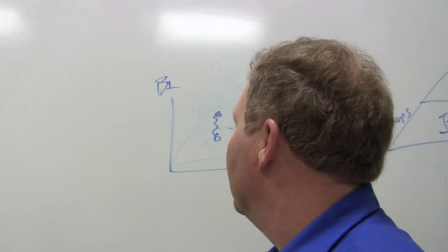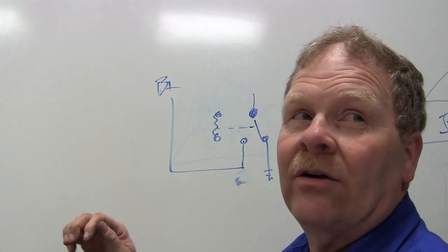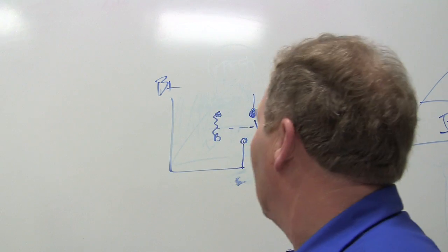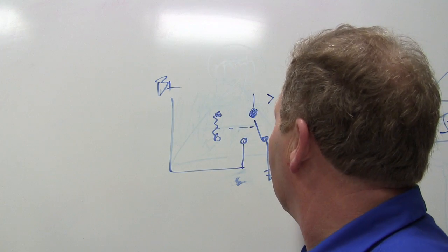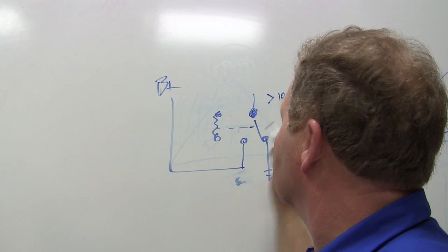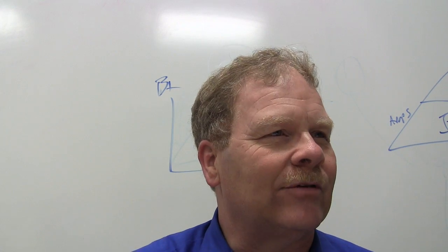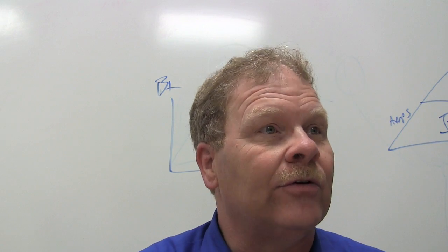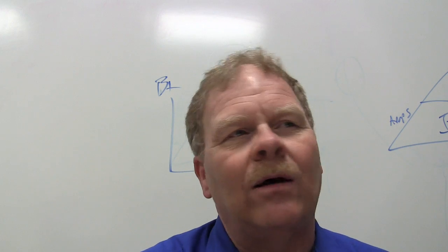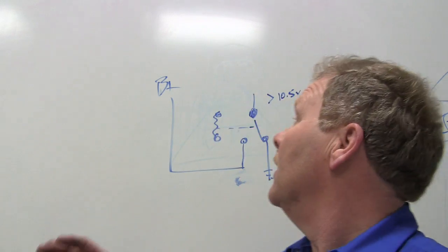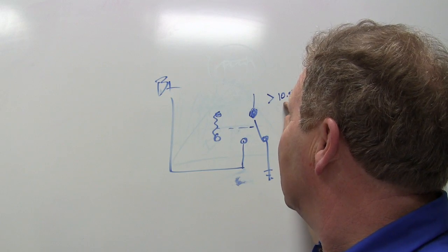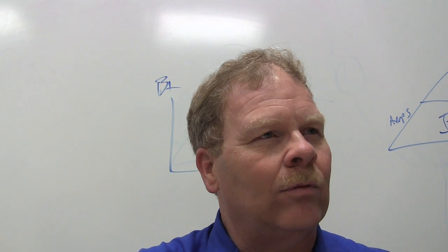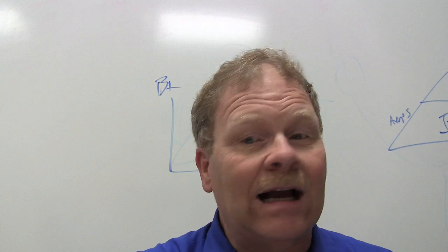And so what I was supposed to do was, with that relay energized when the key's on, check right here, and according to the shop manual, I was supposed to have greater than 10.5 volts. That was Ford's trouble matrix, you know. Whenever you're not real familiar with the system, you try to follow the troubleshooting tree, and that's what I was doing. On that one, I wasn't all that familiar with that particular system at that time. Well, I got like 10.8, and what is your mind telling you? It says I'm supposed to have greater than 10.5, so I've got 10.8. Exactly. And I kept on moving.